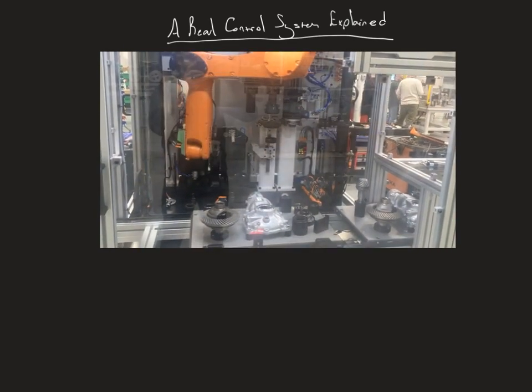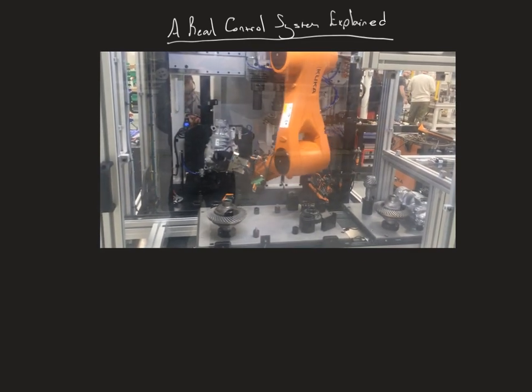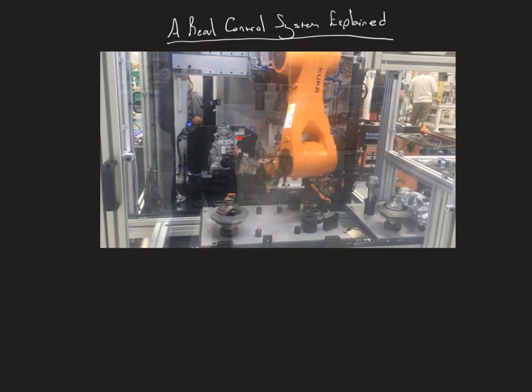Now, that rotation and clamping action is caused by a valve output, just as we discussed previously. And there are sensors on this cylinder which detect the presence and movement of the magnetic flag on the barrel of the air cylinder. So first, the robot is going to pick the pinion and place it to the fixture. And the grippers are also driven by pneumatics. When it places the housing, and those rotated and locked,